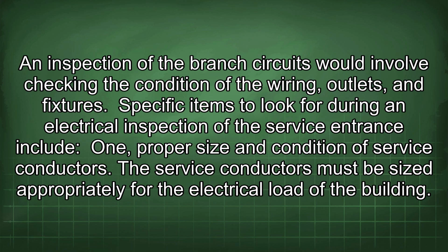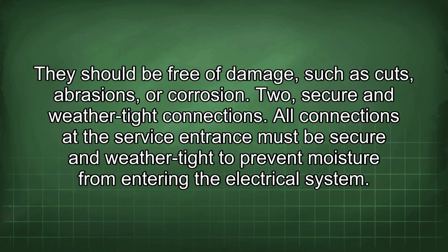Proper size and condition of service conductors. The service conductors must be sized appropriately for the electrical load of the building. They should be free of damage such as cuts, abrasions, or corrosion. 2. Secure and weathertight connections. All connections at the service entrance must be secure and weathertight to prevent moisture from entering the electrical system.